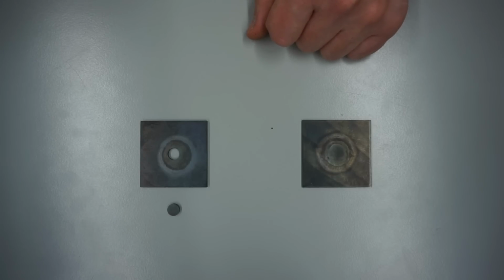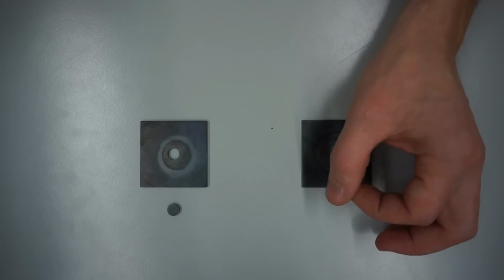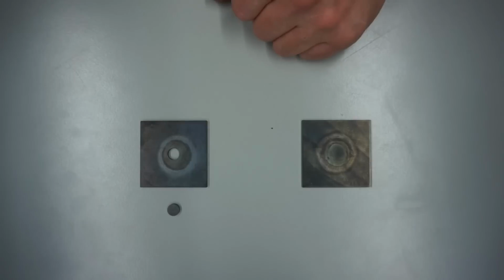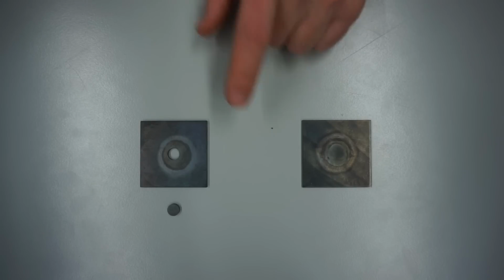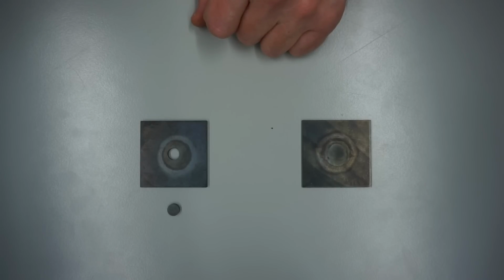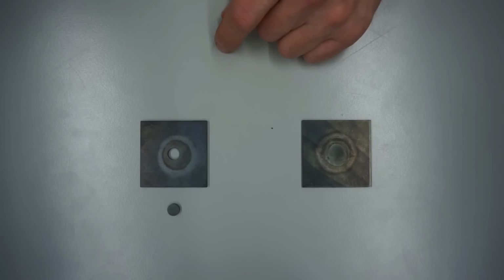In other words, the heated spot gradually experiences radial tension, whereas the hole experiences radial stresses which try to close it. So you might say the heated spot causes a local pinching of the sheet. This is the most essential aspect about welding distortion, which we must keep in mind.